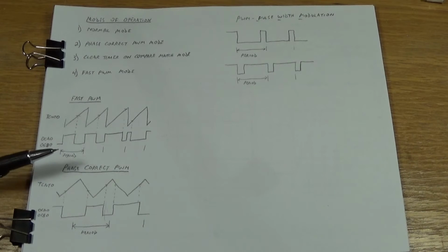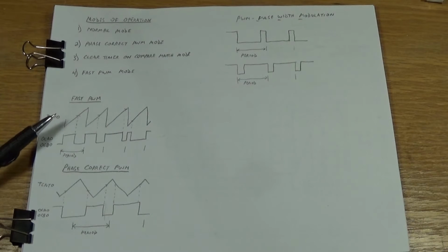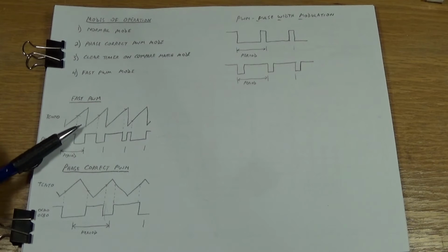I just drew it like this for simplicity, because this is how most PWM is described, is the high time versus the low time. And the more on time you have, say, the brighter the LED that you're driving would be. So that's the fast PWM, and there you can have 2 different outputs from this mode, because you've got the 2 output compare registers, and they can be independently programmed to different values, so you can have 2 separate independent PWMs. And the only thing that's common between the 2 PWMs is this period here, which is between the time that the timer counter register rolls over.